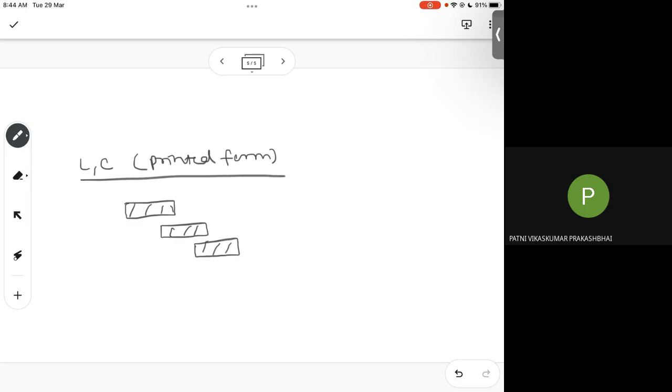So basically it gives me an inductor, it gives me an inductor, it gives me an inductor. Two metals separated by a dielectric give me a capacitor. So if I see its equivalent circuit, it will be something like an LC filter, 1, 2, and 3. So basically I am replacing my simple inductor and capacitor by line lengths.